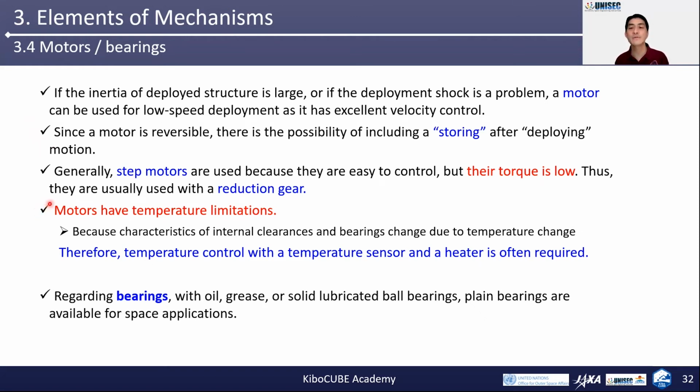The problem is that the motor usually has temperature limitations. This is because the characteristics of internal clearance and bearing change due to temperature change. Therefore, temperature control with temperature sensors and heaters is often required. This may add some complexity to your system.